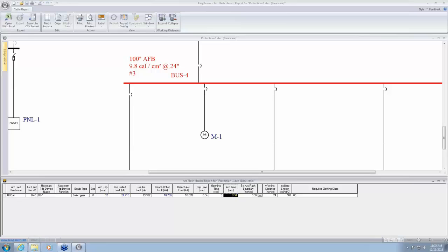Okay, next question is whether knowing that 85% is higher than 100% will help in choosing the setting of the OCPD. Sometimes it can get very confusing because when you're trying to change the trip settings, there are times when 85% current gives you higher energy, and there are times when 100% of arcing current gives you higher energy. It all depends on the shape of your trip curve.